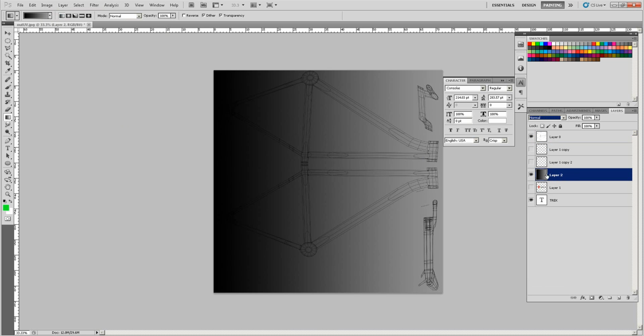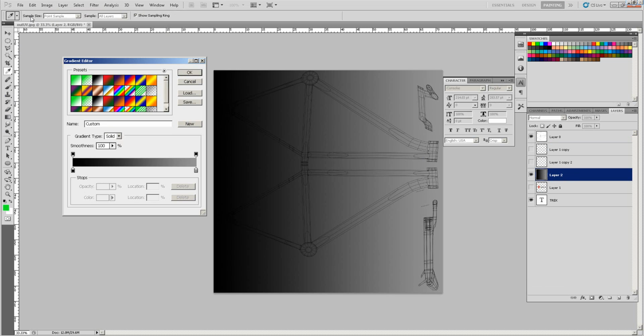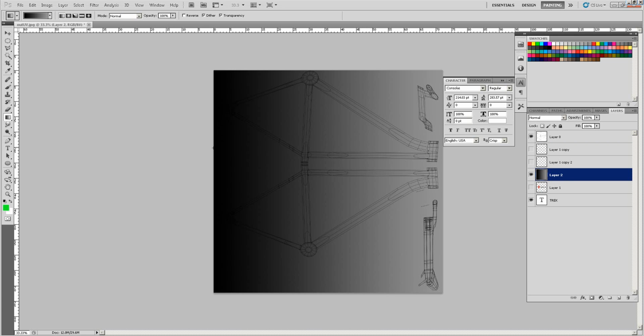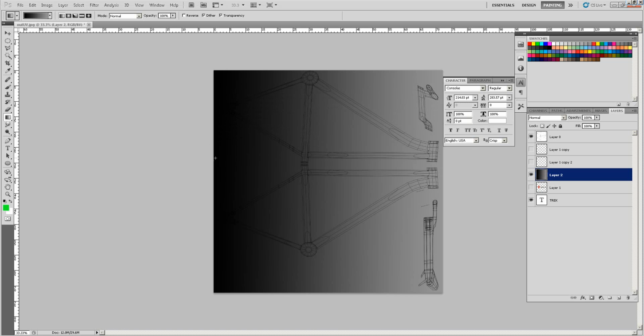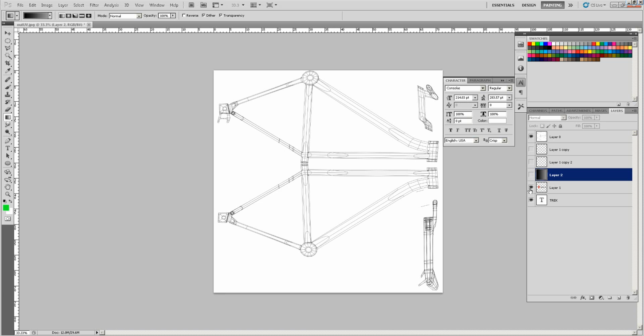And I created a new layer there, and I just double clicked the gradient, which is up here, and made it black to this grey, and then I dragged it across like that. Make sure that you drag it across evenly from this side, hold the shift key and drag and release, because if we do it unevenly, then there will be a line where the UVs hit each other. So then what did I do to get this logo?